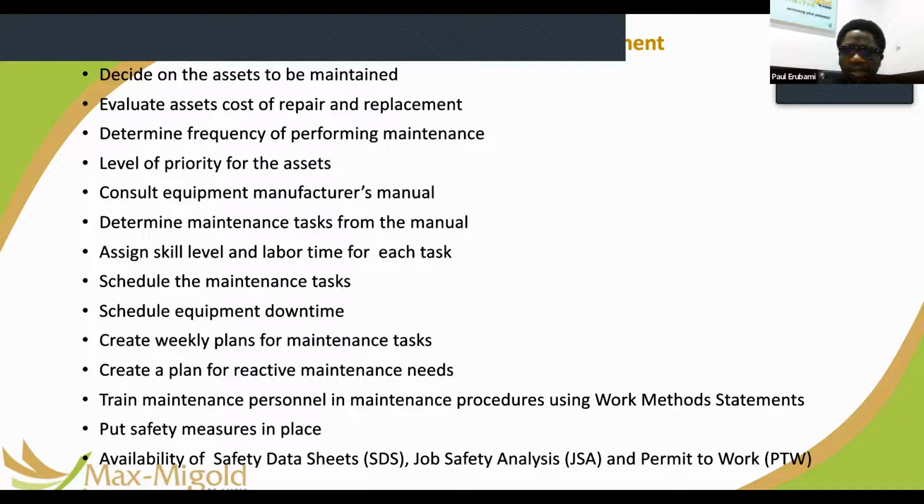And then safety. Every maintenance plan must consider safety, and you must put things in place to ensure that safety is ensured, including things like your safety data sheets. When you use any kind of substance or material in any job, whether routine or non-routine, you must have a safety data sheet.